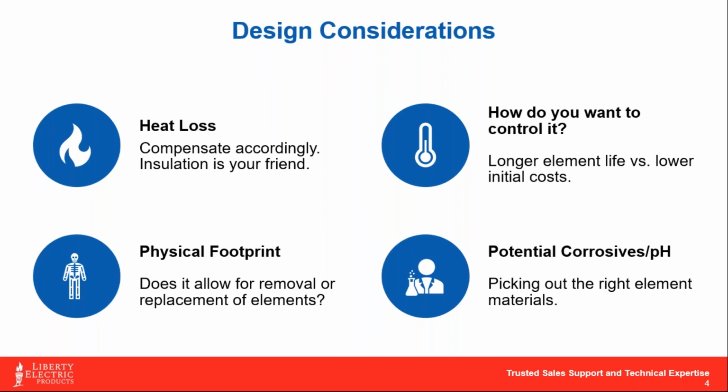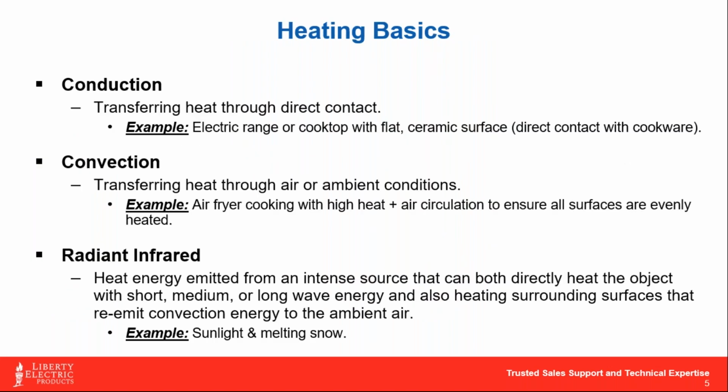How do we want to control it? There are several control options where, hey, I don't need something fancy for this application versus I want precise temperature control and better longevity out of my elements. And then, of course, what is the heating element going to be subjected to? Are there corrosives or issues with caustics or acids where we have to worry about what type of sheath material we're going to use for the heater itself to come in direct contact with?